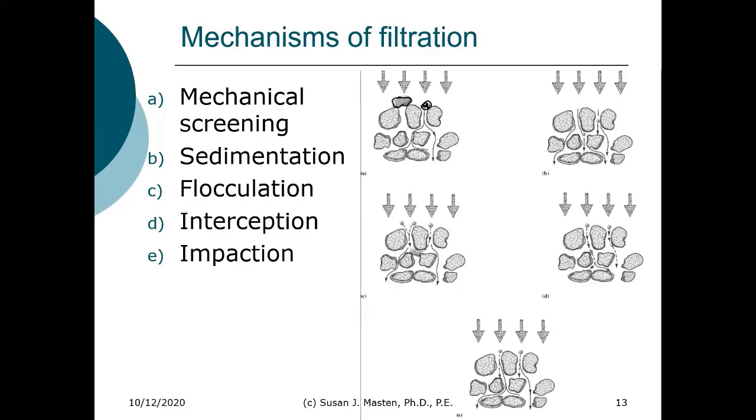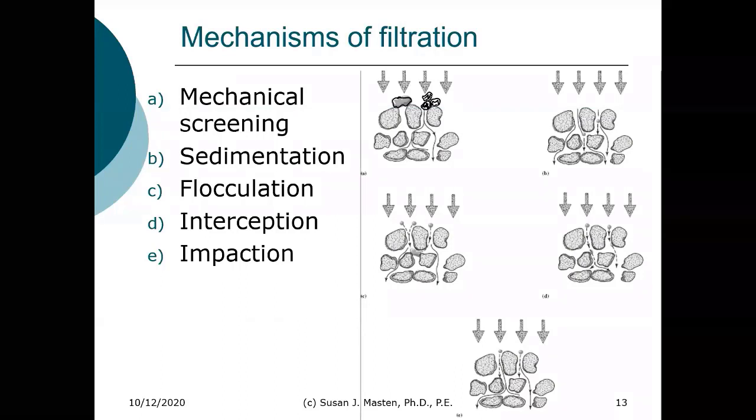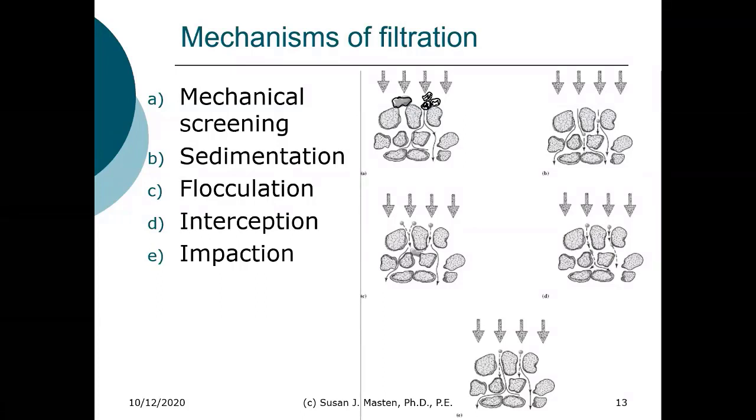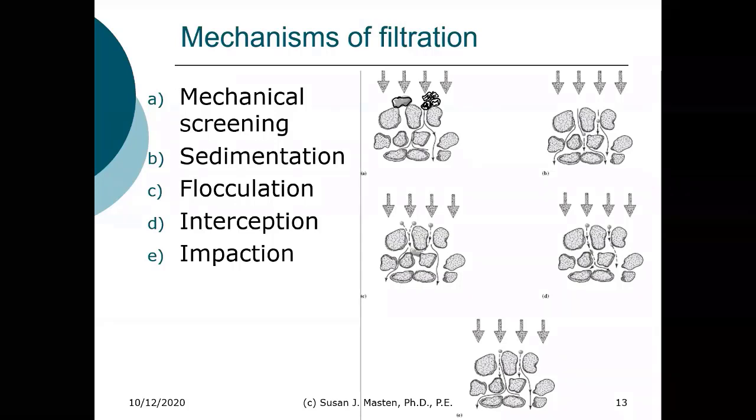You can see this would happen on a slow sand filter, and then you would get this Schmutzdecke forming on the top of your media. Same thing happens when we talk about these mud balls. If you get enough of these together, then you form this kind of clump of material that is difficult to remove.